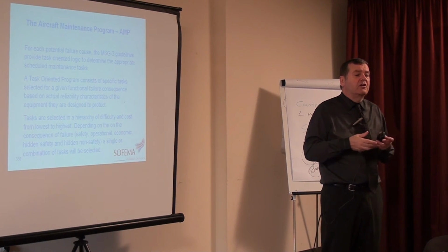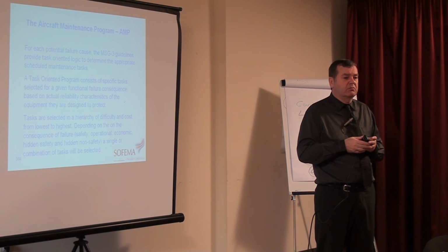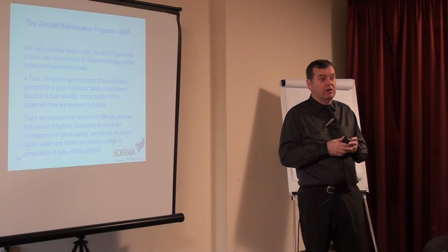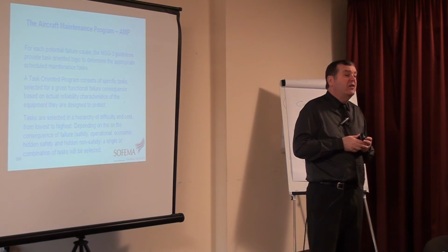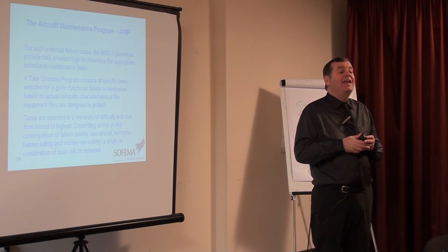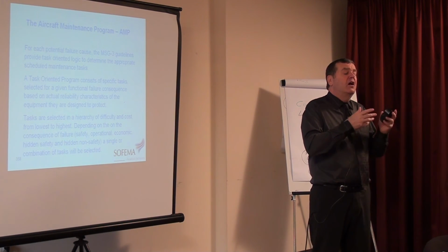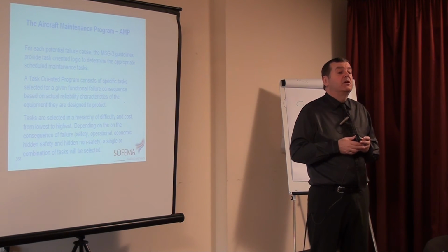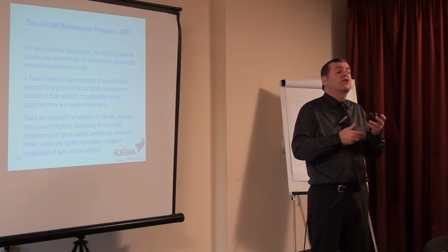In terms of the hydraulic systems, for example, we will have hydraulic pumps which are running all the time the engines are running, producing hydraulic pressure. We also have, independently, electric hydraulic pumps. So if an engine hydraulic pump fails, the electric hydraulic pump can produce enough pressure to operate the flying control. And so it goes on.